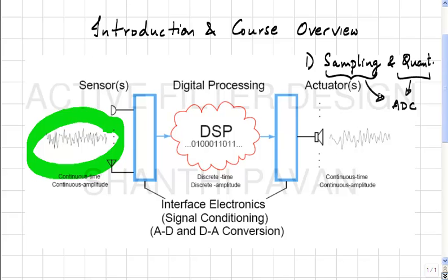Now, what we are interested in is figuring out what to do before sampling, right? We know that whenever you sample a signal, if the sampling rate is not sufficiently high, then there will be aliasing, and therefore there will be a potential loss of information, right. We also saw in the last course that even if there were no signal components beyond Fs by 2, where Fs is the sampling rate, if you didn't do anything, then noise outside the 0 to Fs by 2 band will alias into the 0 to Fs by 2 band, and therefore corrupt or reduce the signal to noise ratio.